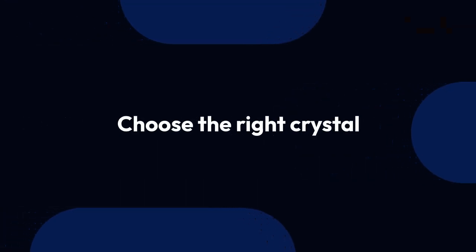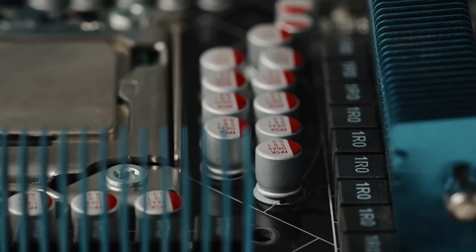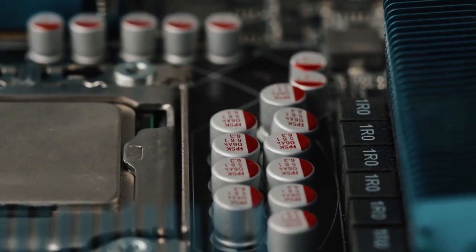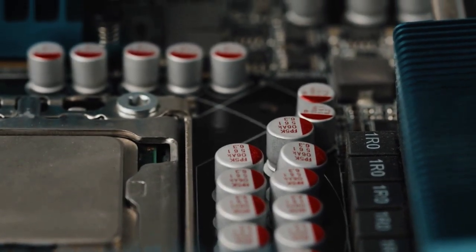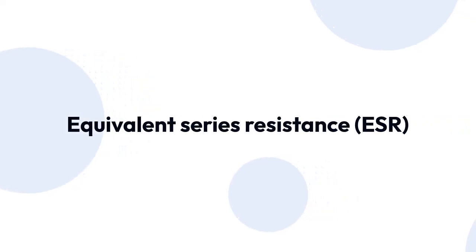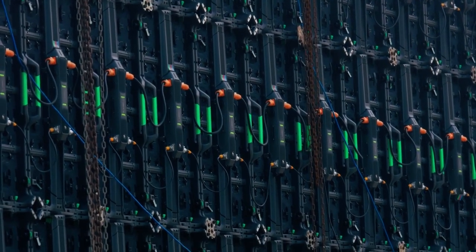First, you need to choose the right crystal. The crystal's frequency is your starting point. Common frequencies for STM32F4 MCUs include 8 MHz, 16 MHz, or 25 MHz. Check your specific STM32F4 datasheet for recommended frequencies. Another important specification is the crystal's equivalent series resistance, or ESR. A lower ESR is generally better for easier startup and stable oscillation.